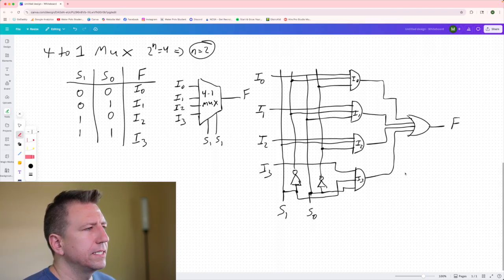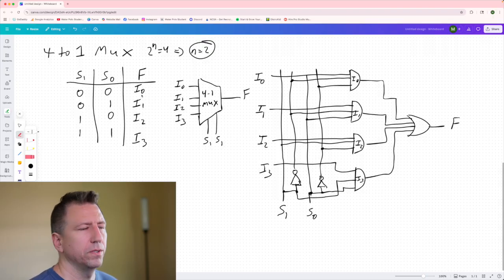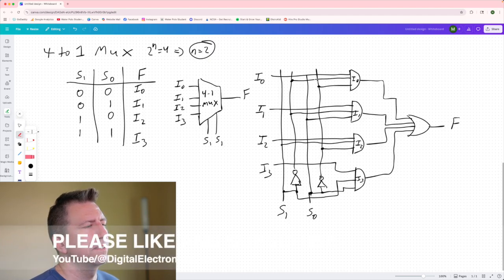So that means that when the particular input sequence comes in, we make those selectors into 1s for the gate that is associated with the input that we want. And so when 0, 0 comes in, we invert both of those zeros and feed those inverted zeros, which would be 1s, into the gate for I0, activating that gate and passing that through to the output.